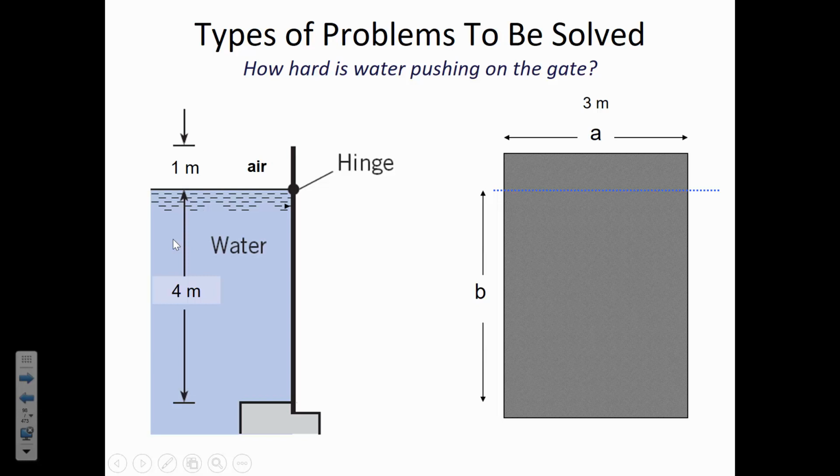When you calculate the moment of inertia of a submerged shape, it's that vertical distance that's more important than the horizontal distance. So I try and help you remember which of the parameters to cube by emphasizing that it's the vertical distance that's, in a way, more important in affecting the magnitude of the force. We'll get into all of these bits.